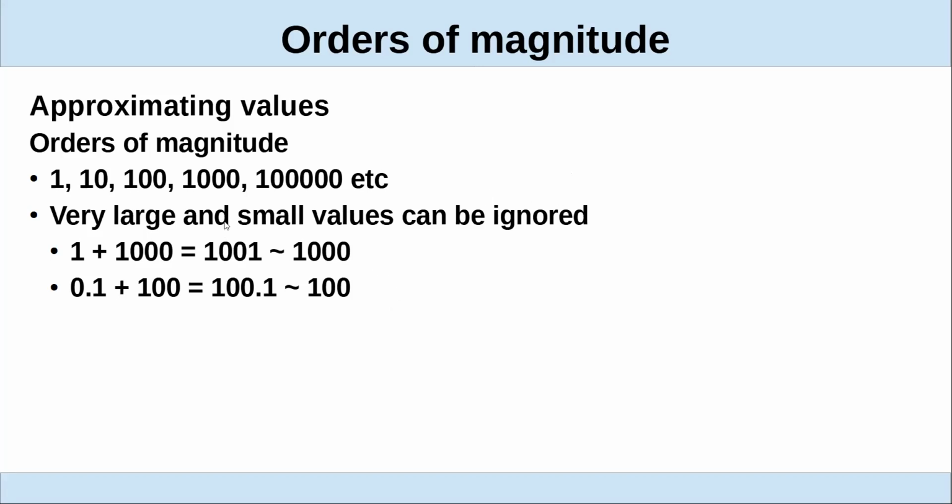And you also need to, particularly on the test, be able to approximate. You almost never need to do anything to 1% or less. So like in this example, if I've got a 1 ohm resistor and a 1,000 ohm resistor, it's essentially the same as a 1,000 ohm resistor. Same is true for this one.